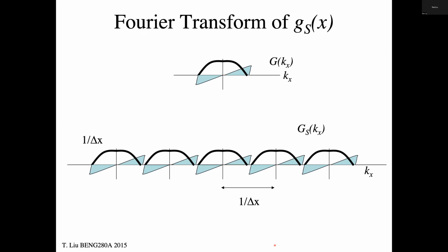When you look at a picture of what that looks like, here's our function, a continuous function g of kx. We have sampled it, and so we take its Fourier transform, and what we get under those conditions is that function here, plus all of these replicants of that function. So at any one value here, you have this function plus what this one is at that displacement.